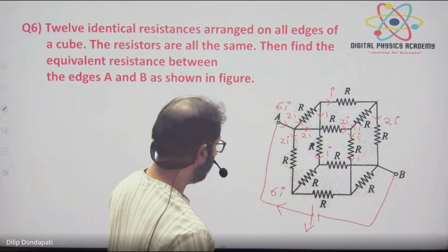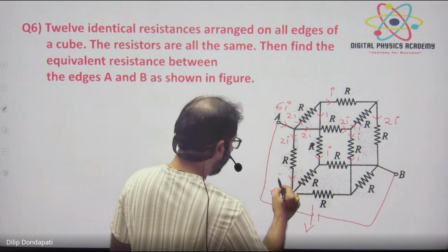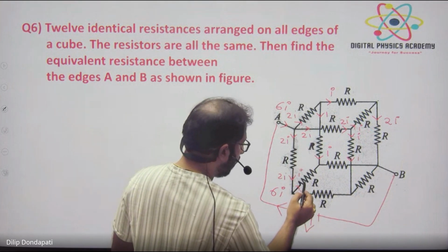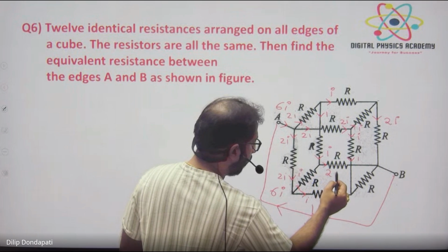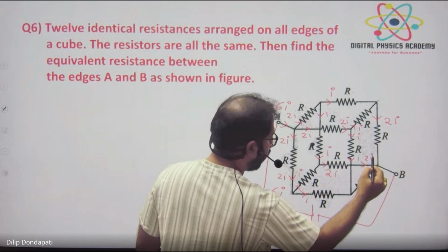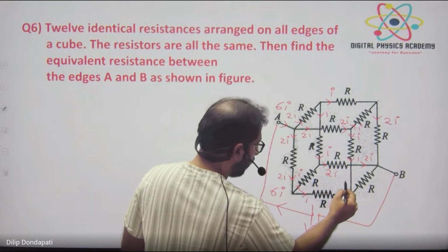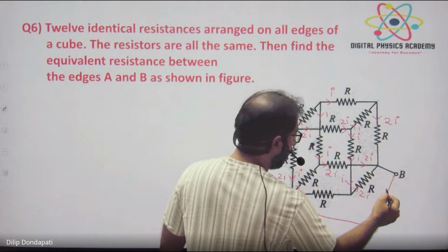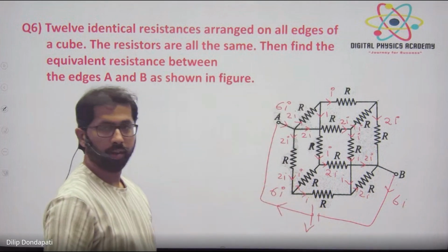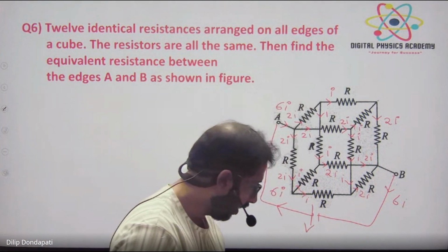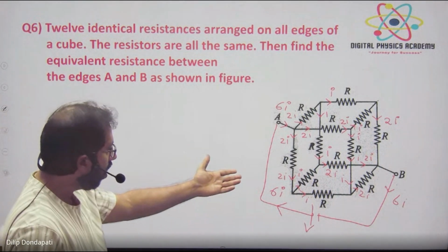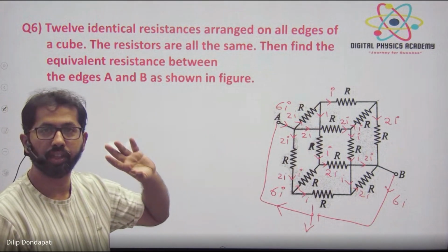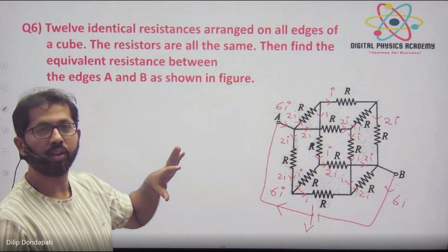Okay, here the 2i again splits into 2 parts: i and i, and here i and i together make 2i. So look, 2i, 2i, 2i, all three together make 6i again. So no fraction will be there. Okay, now you have only one current. There is no I1, I2. So you do not need to find the current. Take the last step directly.